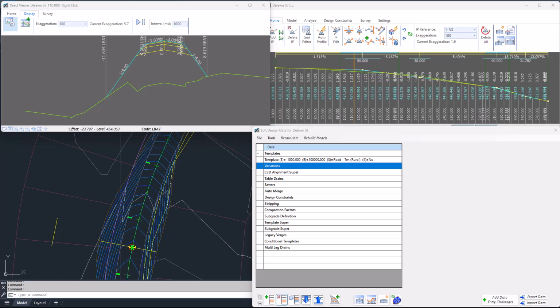When designing your batters or daylights, it's often a requirement to have the projection point where it intersects the surface striking at either a minimum offset or a maximum offset. You can now achieve this with a custom variation.